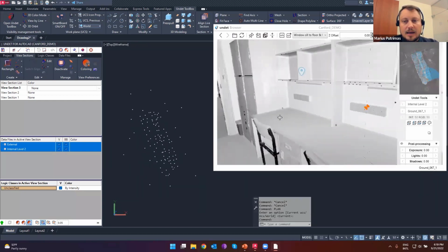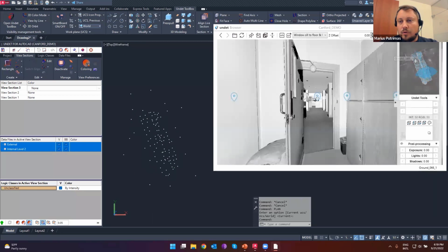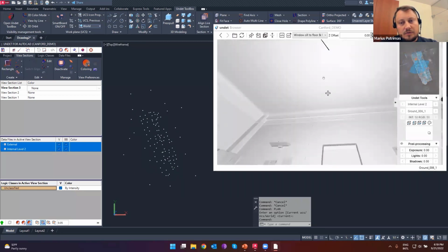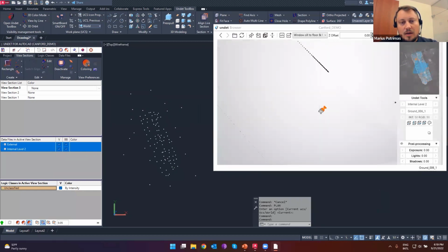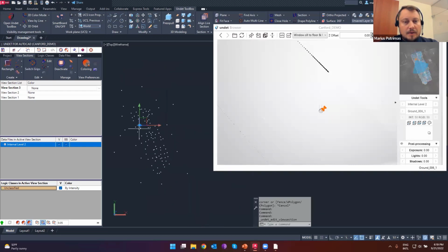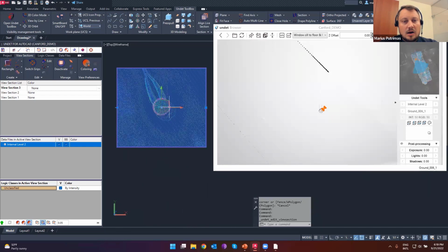And sometimes when you looking for something in some scans, well, let's say I want to see the smoke detector. I just clicking on random scans. My active section is moved to that center where I clicked, and by pressing Edit or Ctrl-Shift-Q, the section grips will be activated, and you will see how this object is looking in the point cloud very fast.